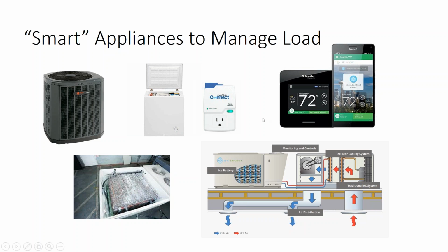But one thing we're doing on this off-grid home is we're using a deep freeze on a timer. The client has a deep freeze and it only runs between 10 a.m. and 3 p.m. And so it's not really ever drawing off of the battery bank. It's just drawing off the solar power, on days where it's not cloudy.